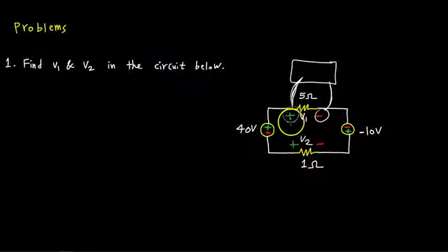And what that means is, if we're correct about this polarity, and this polarity matches the actual polarity of the voltage drop across the resistor, then we're going to see a positive value. For example, let's say that's 5 volts. It's just an example. That's 5 volts, so we're going to see a 5 here on the scope.